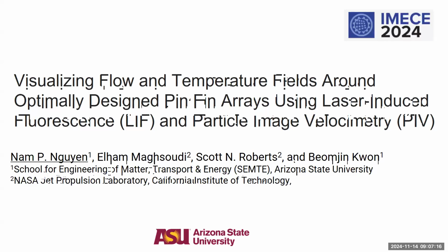In this session, I will be discussing how we visualize fluid flow and temperature fields in optimal pin fin arrays using optical techniques for laser-induced fluorescence, LIF, and particle image velocimetry, PIV. Basically, there are two main parts in this report. First, we optimize the pin fins, searching for the optimal designs, and then we experimentally tested the optimal designs with the PIV and LIF.